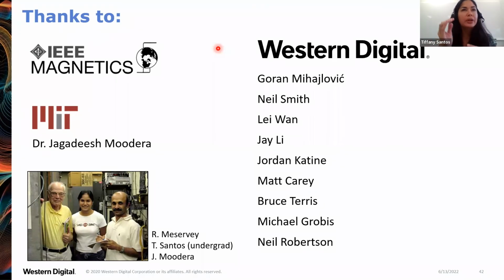The cap, typically the amount of resistance the cap gives to your overall stack is very, very low. In fact, if it has pinholes in it, that's fine. And the function of the cap is really to help give additional perpendicular magnetic anisotropy because it's generated at interfaces. Really, you want it to add very little resistance to your MRAM.